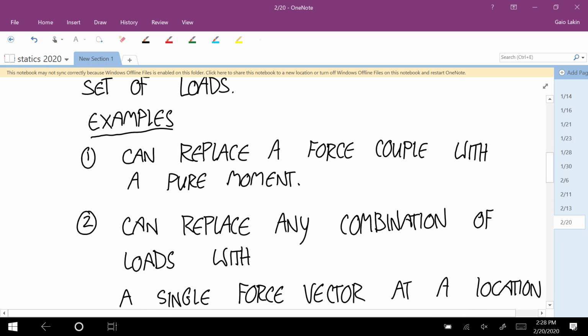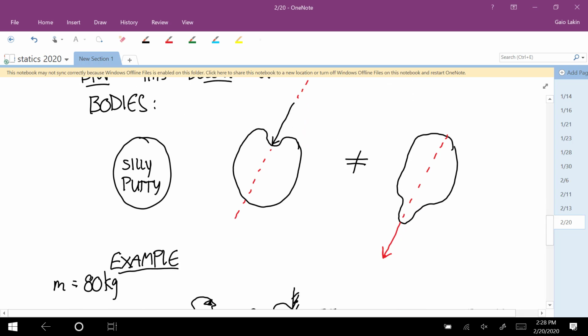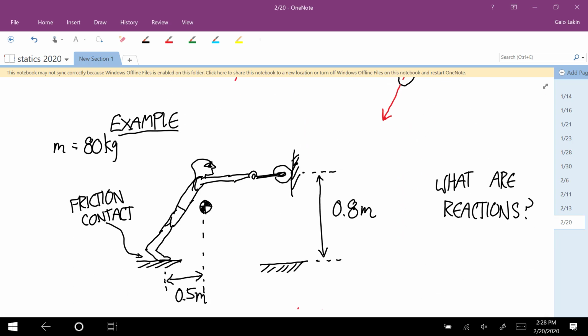One thing I was going to point out since I drew this picture: when you're dealing with rigid bodies, you always treat the weight force like it's acting at the center of mass. All of your mass is multiplied by g and acts at your center of mass. That's not really what happens. Really, there are little bits of force everywhere. It's a distributed load. And so weird things like this happen. In a position like this, the center of mass would not be on this person's physical body, but the system has all of his weight acting at this place at the top of his body.